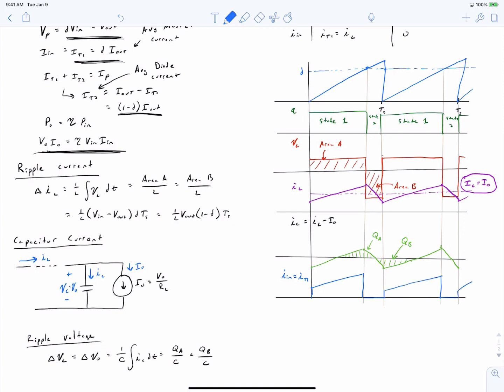And most of the time, our source supply will not like an intermittent waveform like this. Our primary power source would prefer us to draw an average or DC current in most situations, which can mean that we may require a filter on our input.